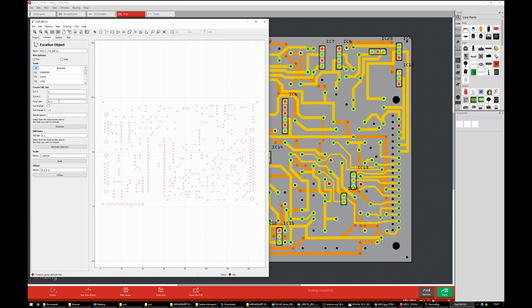Anyway, that feed rate is fine. You can actually adjust the feed rate in Mach3 when you load it in. It gives you up to 300% adjustment, so that's good. This is derived from an inch per whatever, like an imperial thing. That's why it's such an odd number. In millimeters, I don't know what it is, millimeters per second or something. But this feed rate is adjustable, so not to worry what that says really, as long as it's within the ballpark.